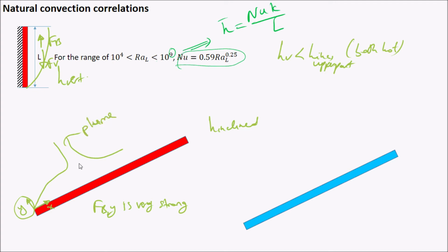This one will break the boundary layer. As it breaks the boundary layer, you will have heat flow in that direction. It means that heat flow is not confined to one space, and as it is not confined to one space, you will have better heat transfer, because the boundary layer is resistance. If you have flow in that direction, you have better heat flow, and therefore you have better H, because the boundary layer is broken.